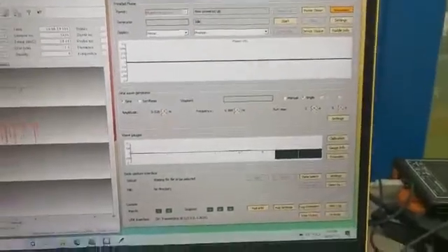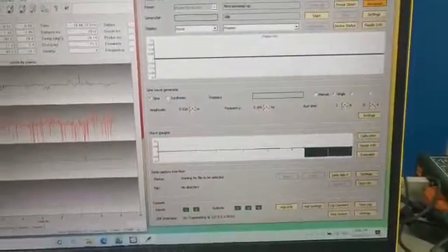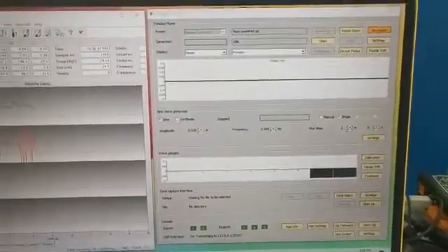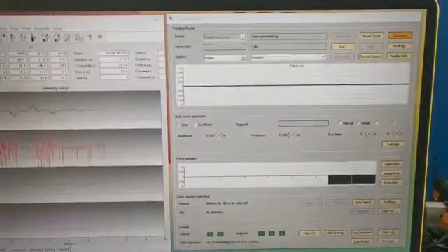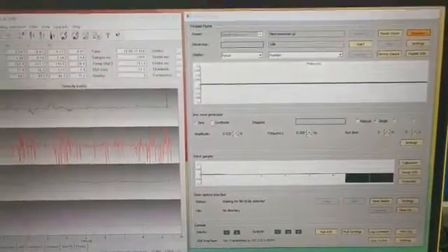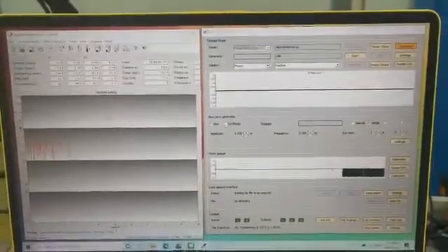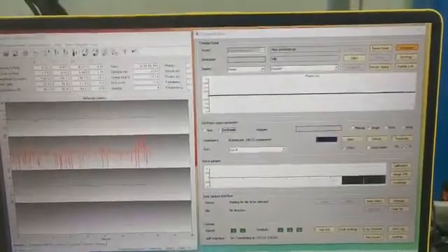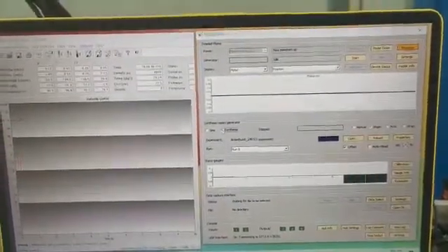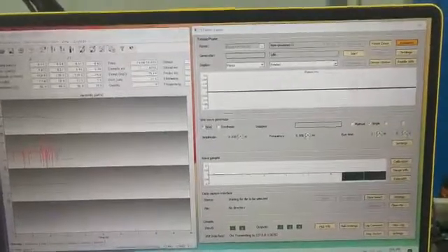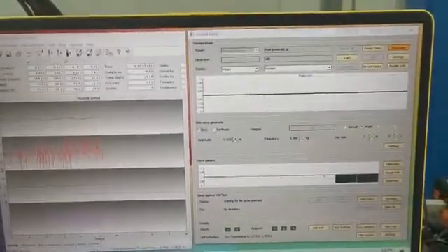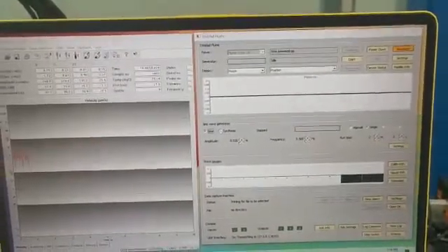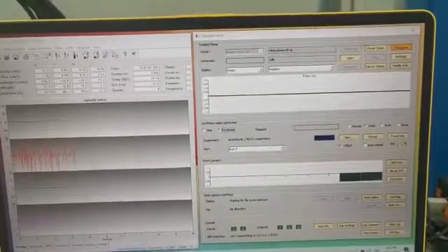Right. So what I'm going to do here now, I'm going to run a random wave, which is called a synthesis wave. A random wave means that there are many different waves coming together. So in this case, we will use a JONSWAP wave. You all could probably go and Google that. A JONSWAP wave is just different mathematical expressions to create a wave. So this won't be one single wave. Like how before we had the sine wave and it was one amplitude and one frequency, this time you will have different amplitudes and different frequencies coming together in one wave.